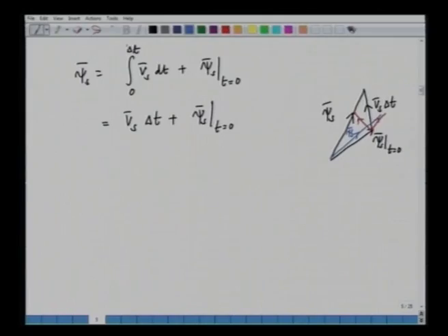So, it means we have control over the flux, and if we control the stator flux, we are able to control the angle between the rotor flux and the stator flux at that particular instant, because the rotor flux has got no option but to follow the stator flux.